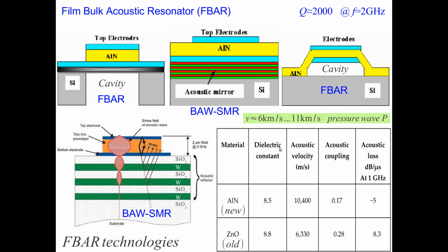But at high frequencies, say, where our smart mobile phones work, there we need antenna filters in the frequency range of a few gigahertz. So 1 gigahertz is a typical example, or 2 gigahertz for a UMTS phone. And here we can build filters as very thin films of piezoelectric materials, from aluminum nitride or zinc oxide.